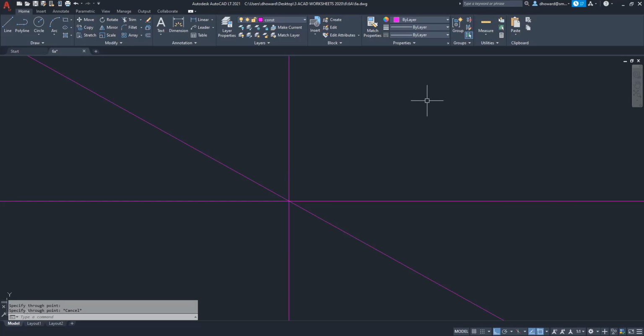Anyway, we can start doing some offsets now. So the main thickness offset is going to be a 1/2 inch. So everything on here is a 1/2 inch thick. So I can get to it: O, enter, 0.5, enter, and just start clicking. So I'm going to click toward the left, and I'm going to click down. All right. I'm going to click one more. I'm going to do another offset.